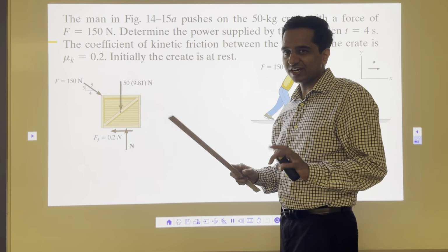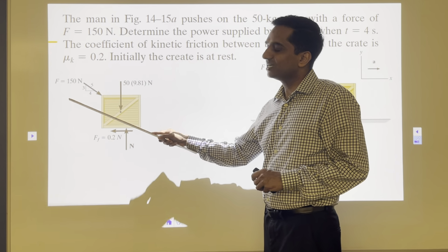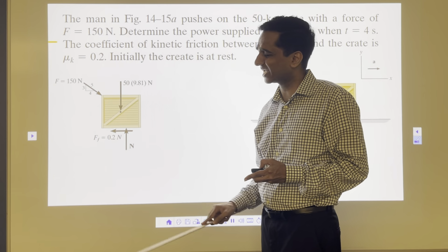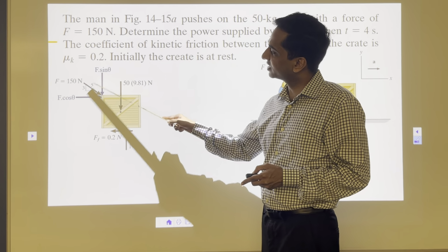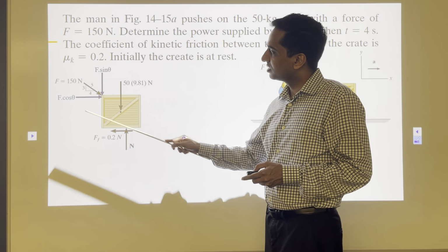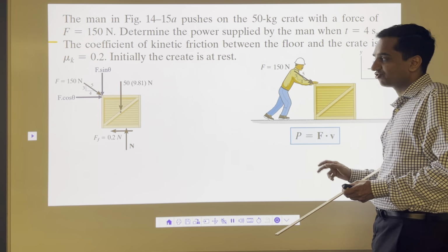So this is a kind of chapter 13 method again. Once we draw a free body diagram, here I need to know the angle. The angle is not directly given. What is given is geometry here, 3, 4, 5, and based on that I can resolve this force into F cos theta and F sin theta. Our objective is to know F cos theta, which we have to use.